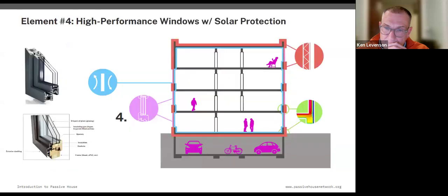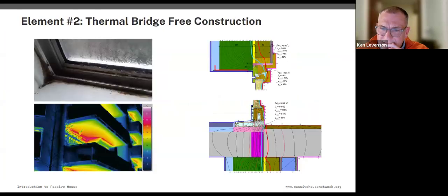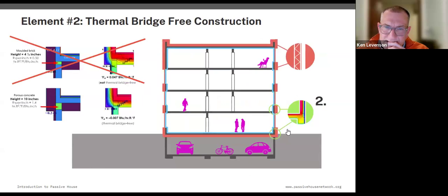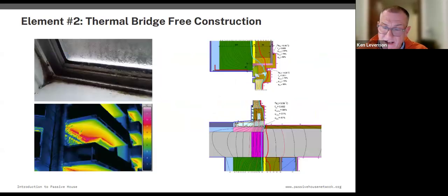We're calculating these different joints and understanding what the energy loss is at these joints and making sure that the coldest point, at that corner, looks quite warm actually, warm enough to not cause any mold growth. So it's really zeroing in on that and doesn't take anything for granted.